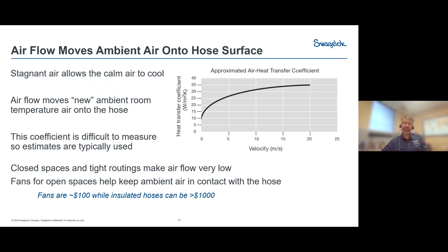Fans are relatively inexpensive, while insulating hoses can be relatively expensive. And so sometimes the most cost-effective way is to simply put some fans where the hose is flowing to, if at all possible.